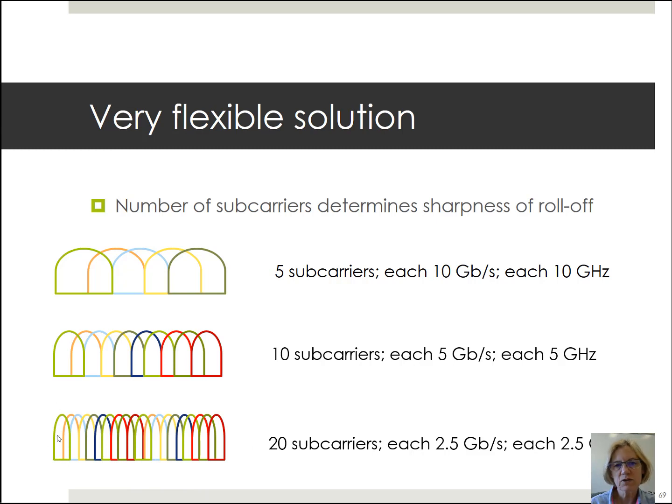So we can see there's a similarity between the OFDM solution and the Nyquist solution, in that we're getting something that effectively is transmitting 50 gigabits of data, but instead of having a very rounded spectrum, which would come from, say, rectangular pulses in the time domain, without necessarily doing the Nyquist cosine shaping in order to achieve a rectangle, I'm getting something that looks pretty rectangular if I have a large number of subcarriers.